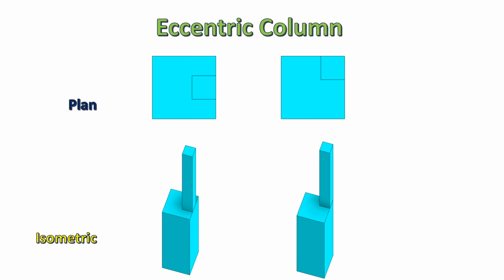In a multi-story building, it is common that there will be an eccentric column. The eccentric column could be modeled as actual in the main Revit model. It is the responsibility of the structural engineers to control structural behavior when transitioning the Revit model to the finite element model. Basically, there are two methods to handle the eccentric column.